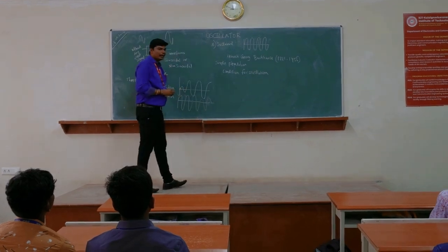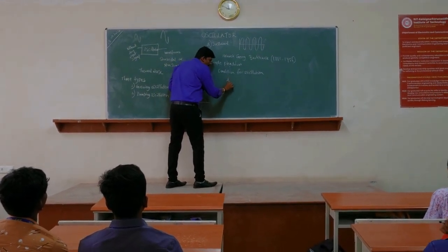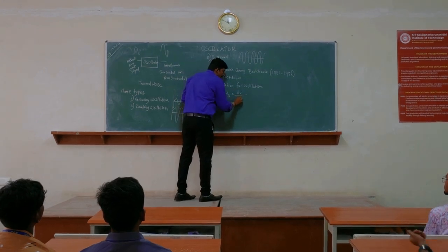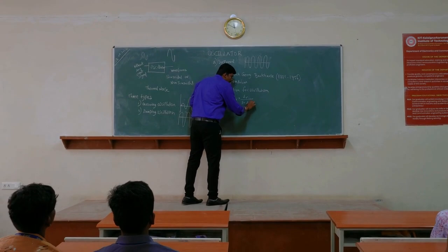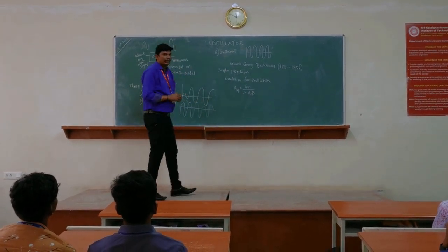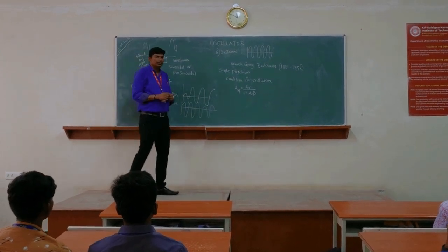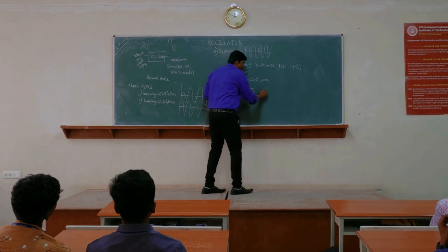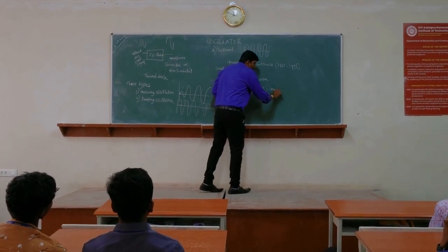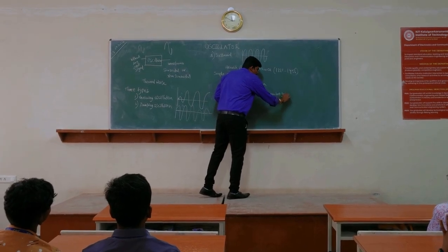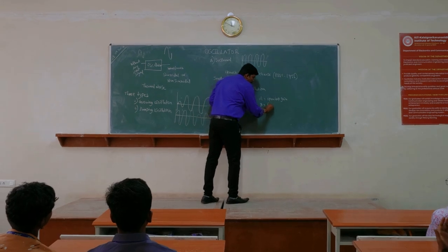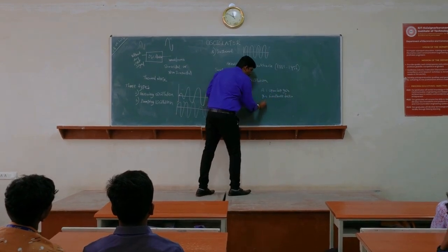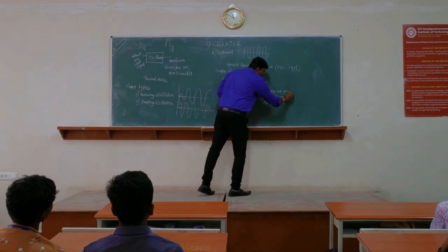We know that if you connect a feedback amplifier, the gain is Af = A / (1 - Aβ). Consider what A actually is: A is the open loop gain and β is the feedback factor. So Aβ together is also referred to as the loop gain.